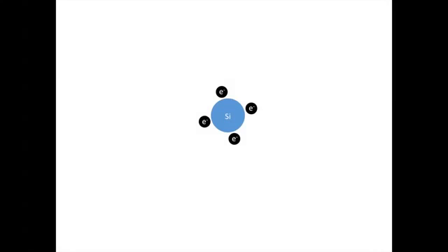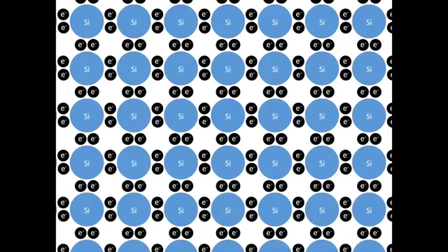We'll start with a 2D representation of a single silicon atom, with the nucleus in the center and its 4 valence electrons. In a silicon crystal, each silicon atom bonds to 4 other silicon atoms around it. These rigid covalent bonds, shown here, keep all of the electrons effectively immobile, and are therefore unable to aid in the flow of electricity. Our intrinsic silicon, or undoped sample, has this material structure, which is why it has a very low conductivity.